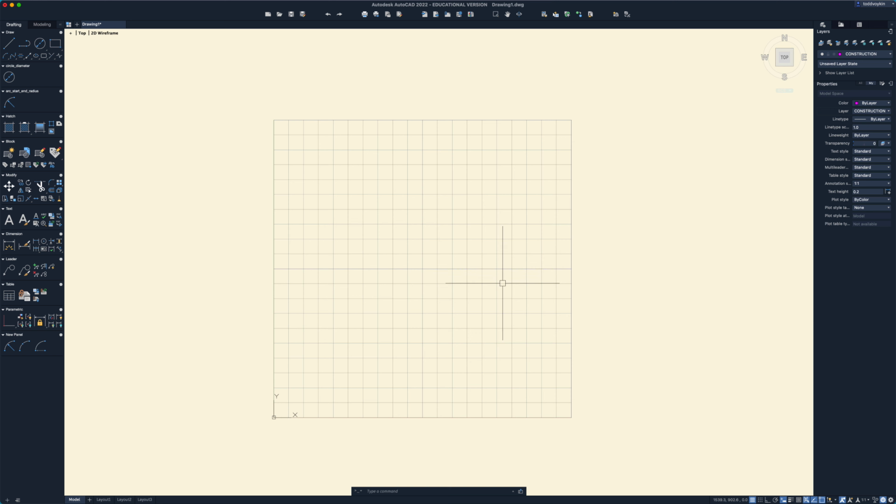All right, so we could draw these three views all on basically the object layer, just using the dimensions that we have, but we're going to do it using guidelines or construction lines and what we call rays. So that's the first line that we're going to make, is a ray. So move your cursor somewhere into your drawing space and just type R-A-Y, and hit enter. Now a ray is a line that starts at a certain point and then continues infinitely in whatever direction you set the ray up.